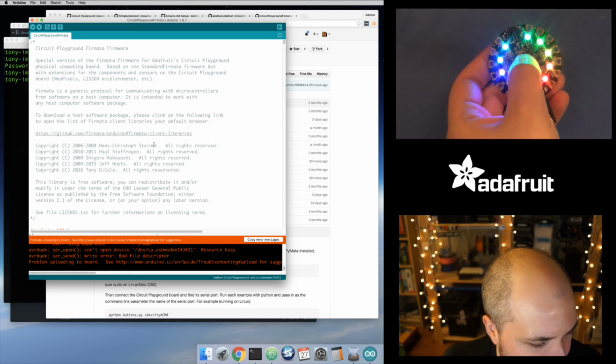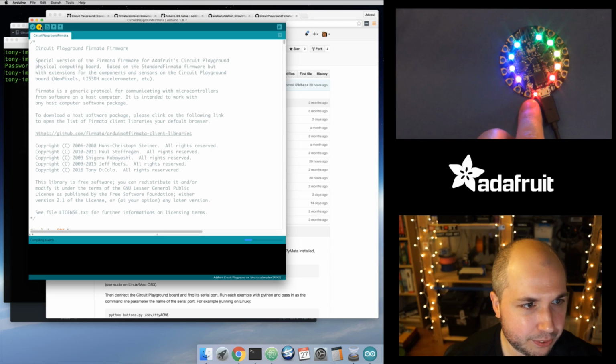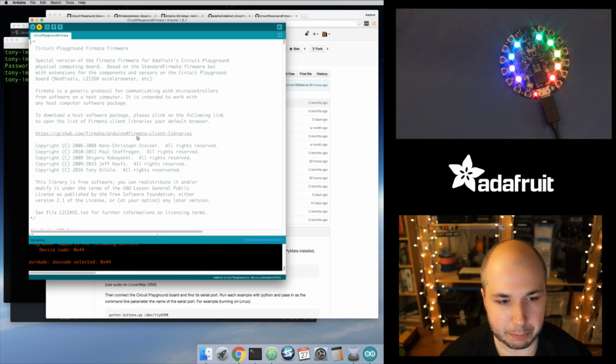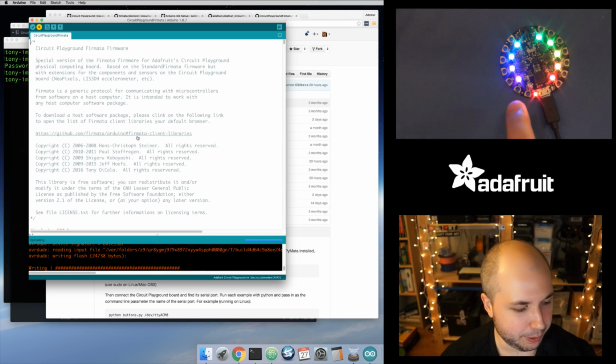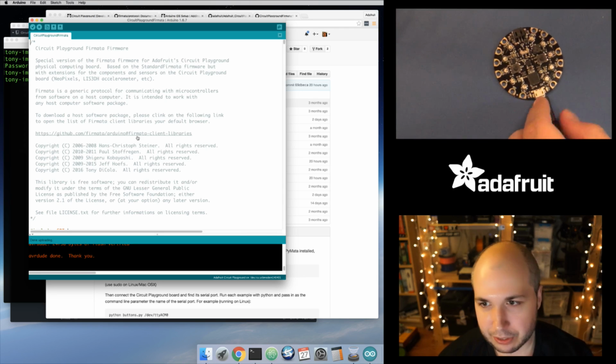So when this happens for me, I just double press the reset button. Now the red light pulses, and now I'll do the upload, and this should go. You need to make sure to do it quickly because after 10 seconds the bootloader stops and you'll have to do it again. So okay, that worked. And you can see everything kind of turns off.